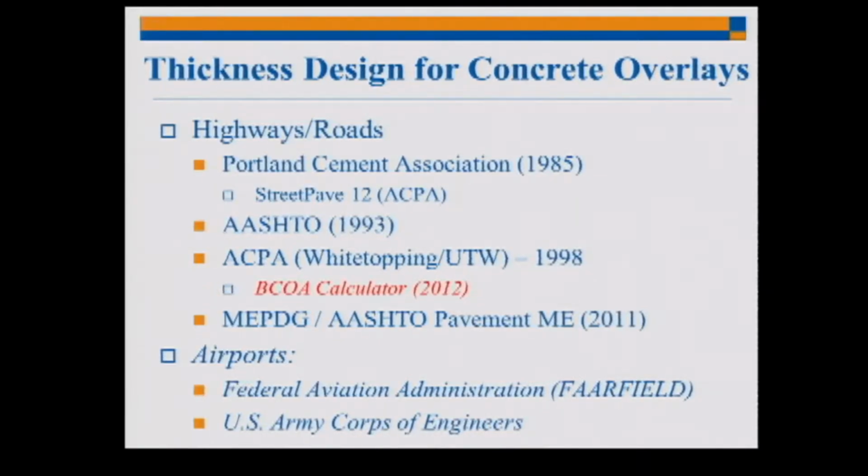Well, there's a fair number of design guides that are available, but not all of them do overlays very well. Some of the ones that I would recommend, and we'll talk briefly about, are probably the ACPA design guide, and they have a web calculator that you can use on a website now. The old AASHTO method can do overlays.